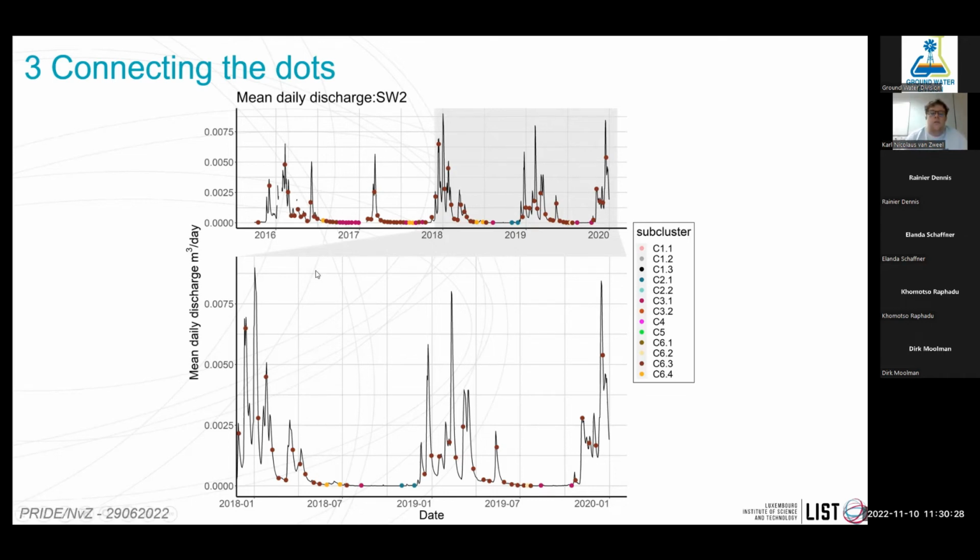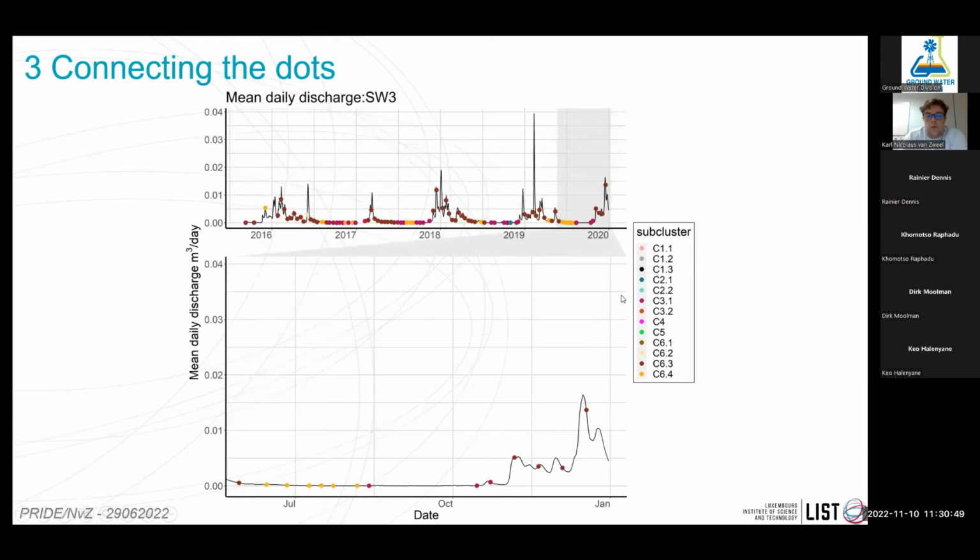Because at the end of the day, we aim to do what is called a stream flow separation, and usually it's done through stable isotopes, but you can also do it through chemistry, but you have to make the assumption really that you have a conservative tracer, which is actually not the case for most solutes or natural tracers in a system. So you have to separate the mixing variance from the chemical variance, right? So this is the aim, to account for the chemical variance, and then what we're left with is mixing variance, and then we can start understanding what generates stream flow in the system.